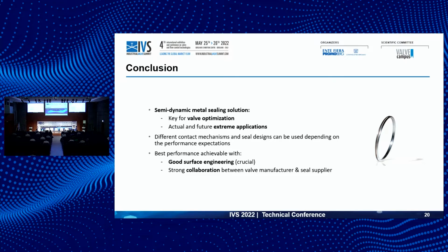We have a path in the double offset butterfly valve, and we have an excellent return of experience on the double offset butterfly valve in cryogenic applications for liquid methane. Typically, KSB, for example KSB Amri in France, is one of our big customers, and I think we delivered 1,000 seals. So normally, I'm not so worried about that. But it will be tested, yes, for sure.